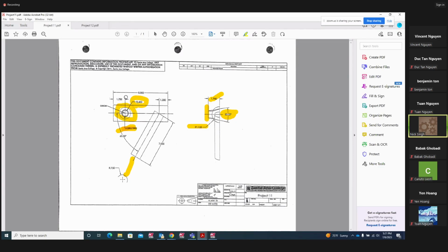Now from here, Z minus 1.7, I can create this arc here, which is your radius 1.125. If you look here, that's your radius 1.125 at Z minus 1.7. From the origin, I'm going to go in the construction plane right and create this arc here and this arc right there, and they both have radius 1.125.